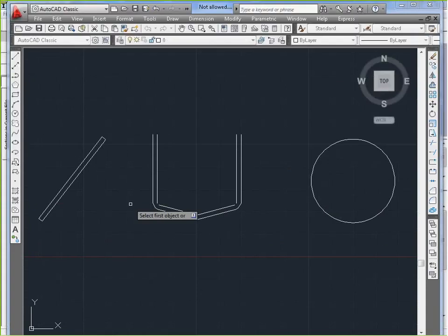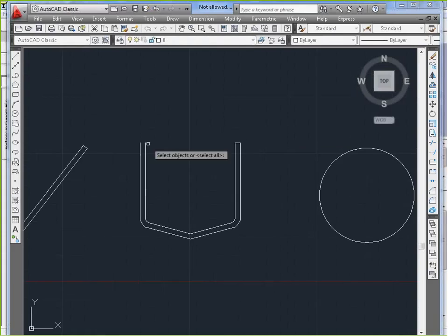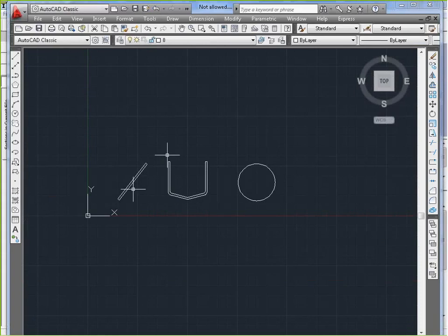And I'm going to fillet this. So I'm going to just do a fillet closure on this guy. And I'm going to do a fillet on this side. And then I'm going to just draw some lines to connect the top portion there, because it still wouldn't have gone across had I not closed it off. And I overshot it. Sorry, we're running a little low on time, but I want to make sure I can show you some of these different pieces here. And so I've got this in place, my closed U shape, and then my big opening here. I want to make this more of a pipe, so I'm going to offset this, and I give it a thickness.